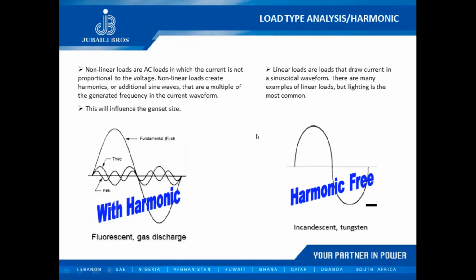This is a different subject, but it's just to grab your attention that this does affect the genset size. Nonlinear loads, guys, are loads that change their impedance with the change of voltage. So current is not actually proportional to the voltage, which will induce different harmonics and it will affect other loads and the power source as well.